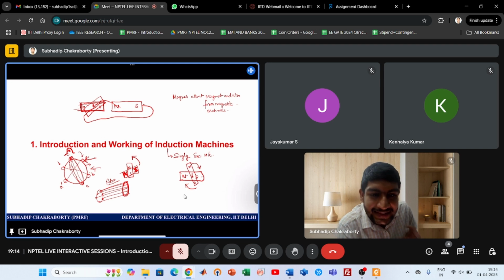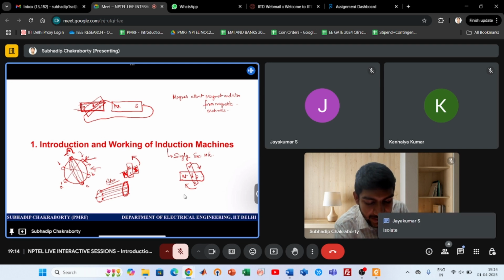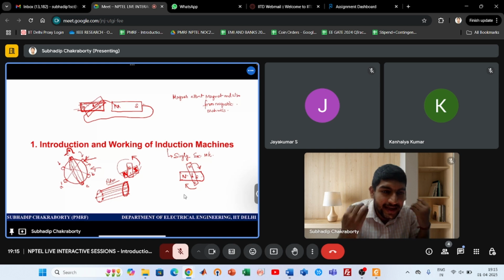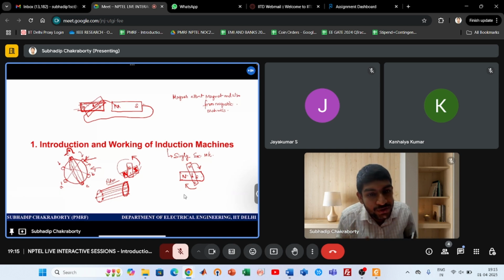But is the rotor doing anything else? I just told you the concept of magnets. In any rotating machine, purposefully you have to create virtually two magnets, one on the rotor, one on the stator. If it is not so, how can it rotate? I told you, one moving magnet and one magnet has to catch it, like a donkey and a carrot. The carrot moves forward, the donkey continuously tries to trace it. So long as you carry the carrot forward, the donkey will move.